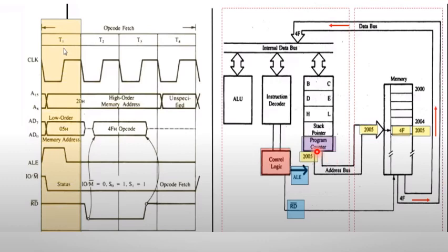I have told you that once this address is obtained, it is first to be noted by the microprocessor. The address will be coming through the address bus. The lower order address is to be noted first by the microprocessor. So the ALE signal goes high during the first half of the clock cycle, right? That is, here it is during the T0 state.